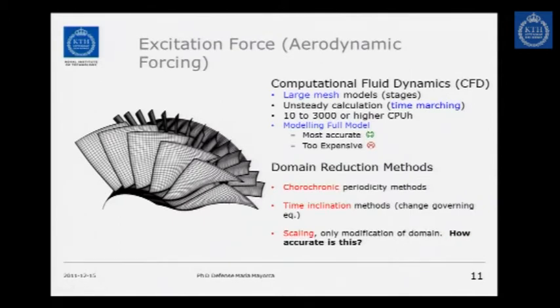So this is about the structure. The other thing that we have to know is the excitation force, and it comes from the aerodynamics. In this case, the most common practice is to use computational fluid dynamics. What happens is that you need to model a very large mesh because you need to account for stages.